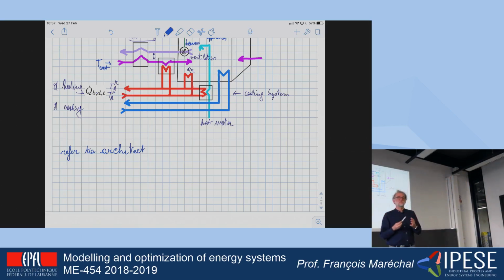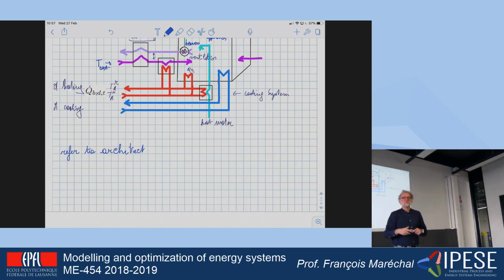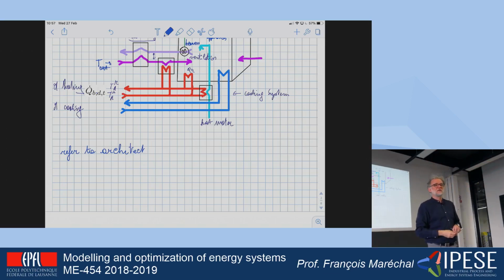We will assume that everything is at 21 degrees C. And then what do you need? Why do you say that there are variations? External temperature. So you need meteorological data. You have to have a profile of the variations of temperature, and this is not so difficult to obtain. Meteonorm, for example, measures external temperatures in a lot of places, so it's easy to obtain an expected temperature profile throughout the year.